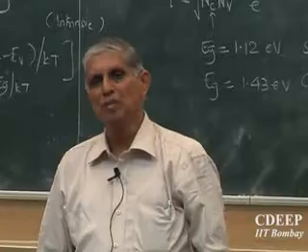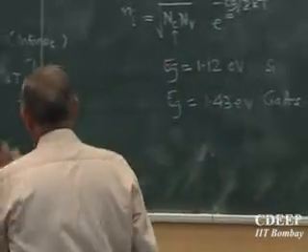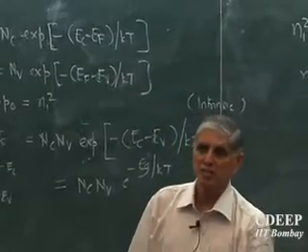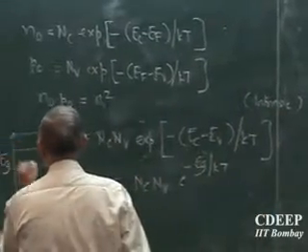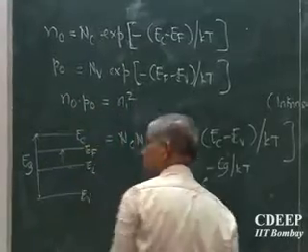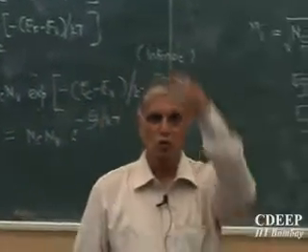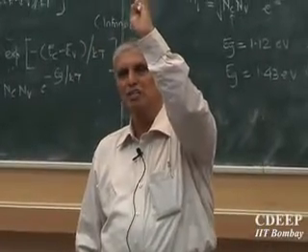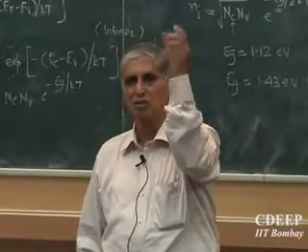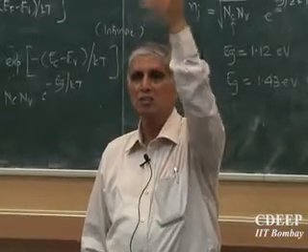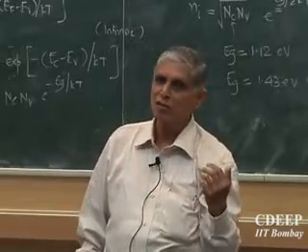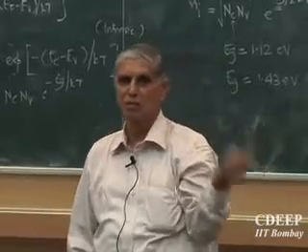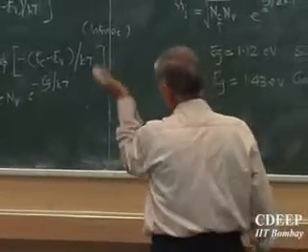So this essentially means that if I dope the material now, the Fermi level, as we saw yesterday, moves towards the conduction band. Yesterday we showed you the Fermi function, and if the electrons are larger in number, the Fermi level moves up towards the conduction band, and therefore there is a larger probability of occurrence of electrons. So 1 minus F(E) went down because the number of electrons is higher, so 1 minus F(E) is smaller. Now this means EF started moving up.